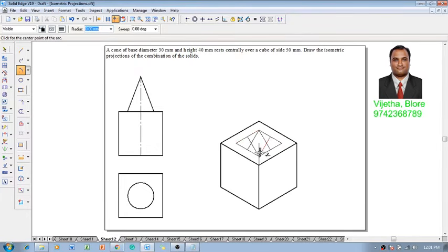So now we can observe that sometimes we are going to get the arcs on the different side which is not required. So sometimes we have to try repeatedly. Now we can see that we have completed the two different arcs. Now we are moving to the third arc, and finally the fourth arc has been generated. After generating all the required arcs, make use of a line command.